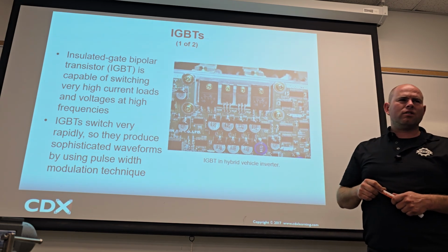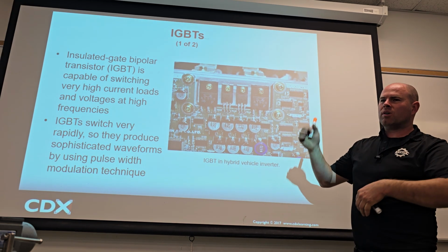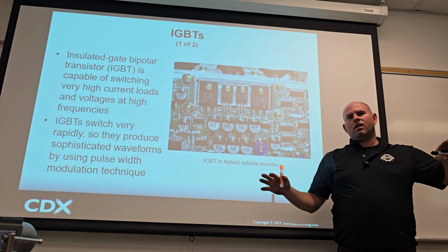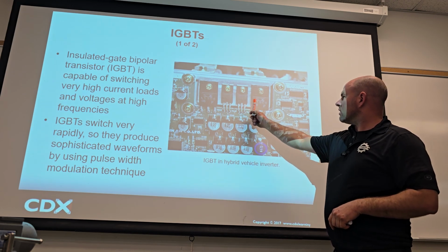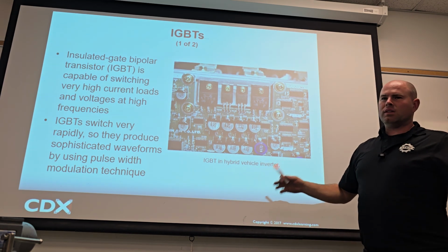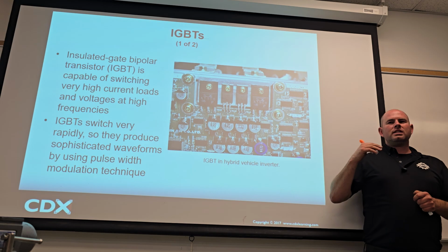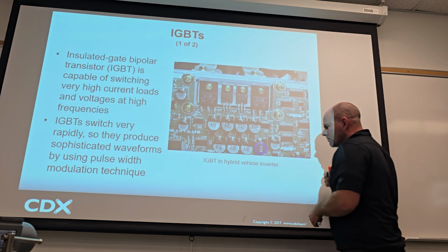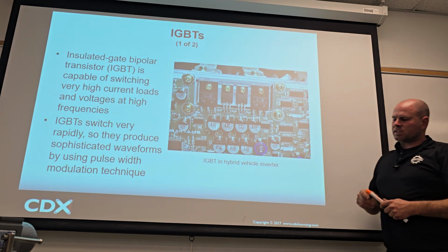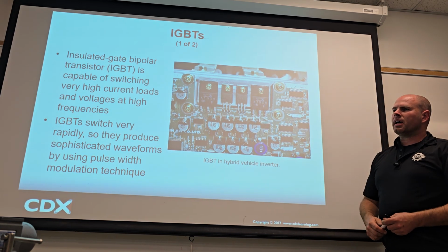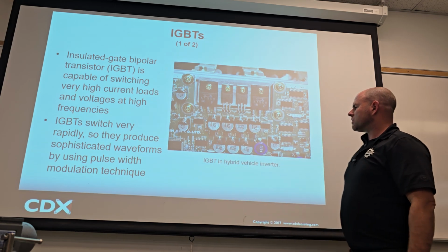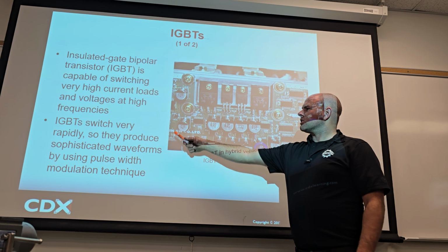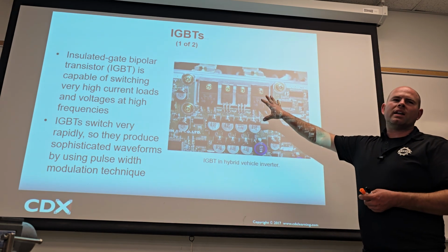And they'd say, oh yeah, how do you know? Well, I measured this and I wasn't getting the correct AC waveform out of the inverter. That's it. You don't go like, oh, it's this IGBT or it's this. No. It needs a new inverter with the whole assembly. That would be realistic. Cool. But similar to before, you don't just go in and say, let me test these transistors and let me test these chips and let me test these resistors. You'd never go at it like that.